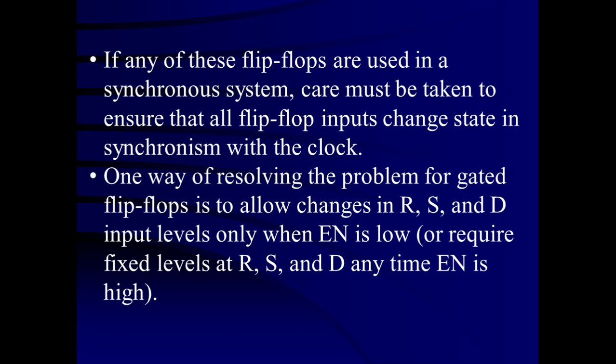and you cannot change the input, otherwise the output is also going to change. So either you have to keep this input constant, or the input level has to be fixed at a constant, stable, unchanging value, while the enable input is high. When the enable input is low, you can change the input. This is the problem with the clock flip-flop or gated RS flip-flop. Both these problems can be overcome if we utilize edge-triggered flip-flops.